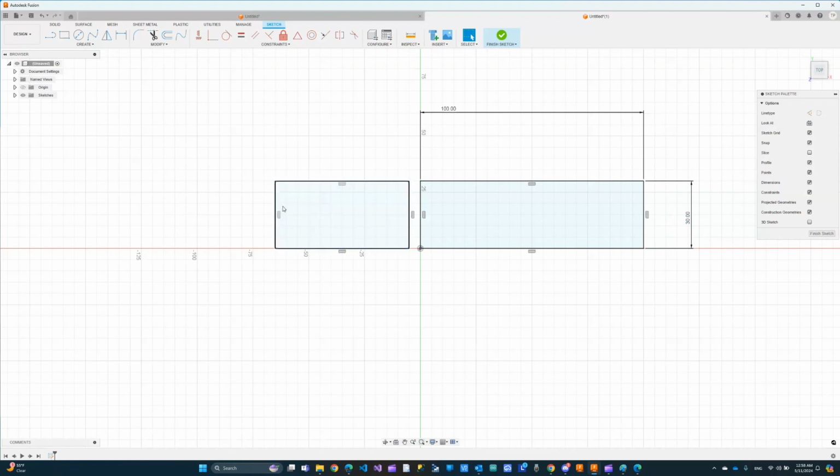So let me go to this rectangular here and use the dimension again. I'm going to click this line, and you can see I can do the same thing. I can just type in a value. I can, let's say, do 50, and that'll work. But that's not what I want to show you here. What if I click the 50 here, and instead I change it to D1? You can see it's going to pick up the D1 automatically from here. This 30 is D1.